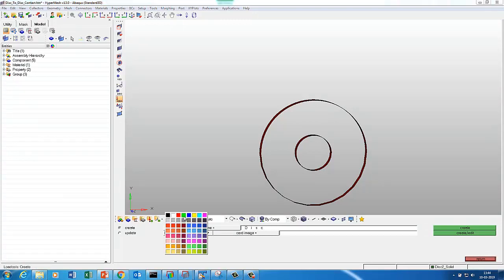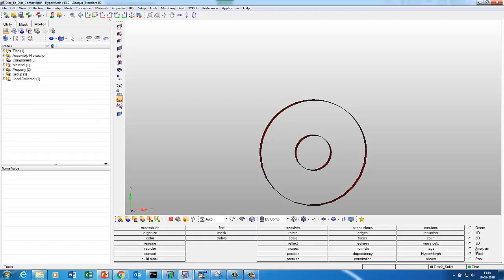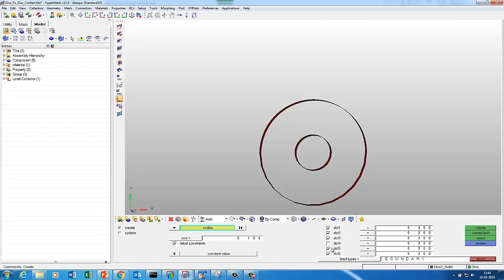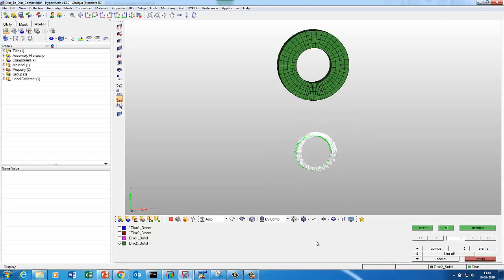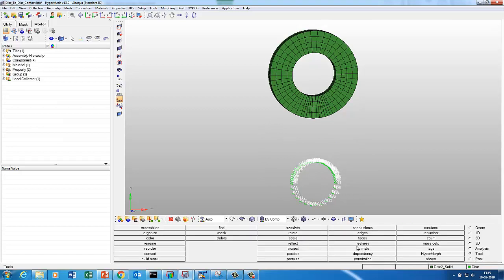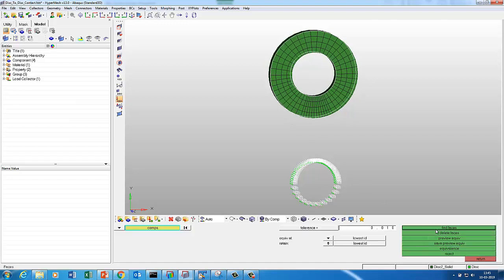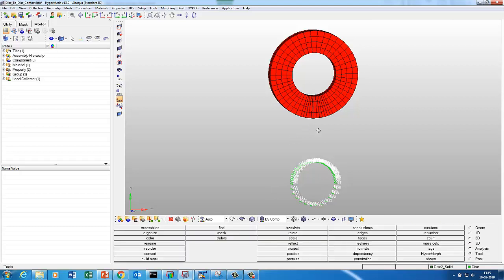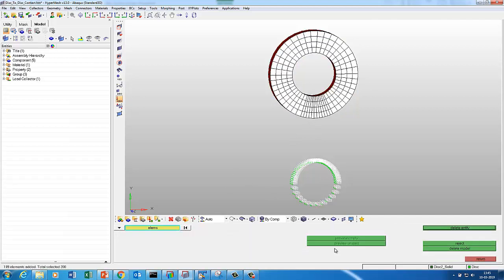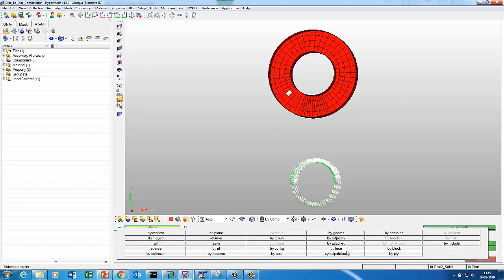This is actually all translation constraints. So analysis, I go to the constraint and I say all translation constraint on this node. So create. So we constrain all XYZ DOF. Now tool, faces, I delete it. Now I'll put this 2. I say tool, faces, I say component select, find faces, and then I also do one thing, I'll delete this. I'm deleting this because for selection it will be easy for me.